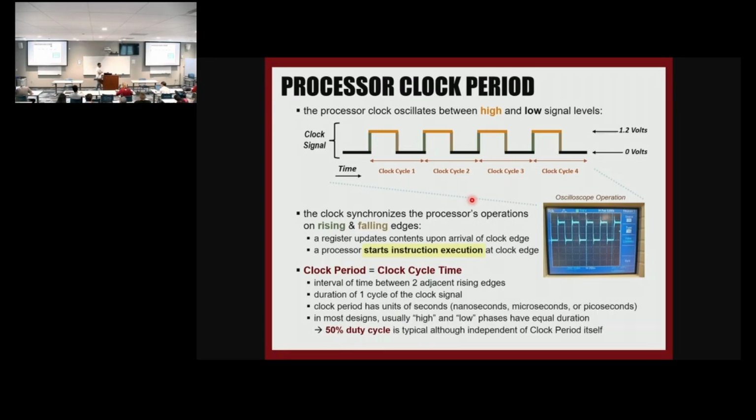So registers in a processor are updated in one clock. Usually you say at the rising edge of the clock. So when you have the rising edge of each clock, you update the registers, right? Literally when you have SystemVerilog code, you write always at posedge of clock, do this, do that, right? At the hardware level, you simply say do this in the positive edge, and you can also say do this in the negative edge.